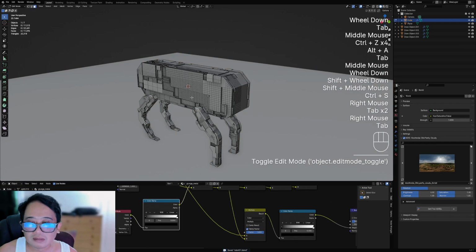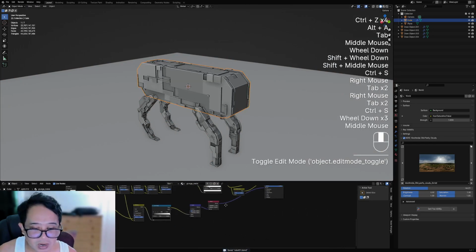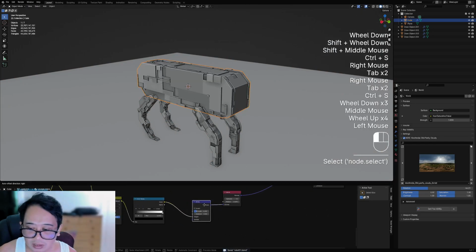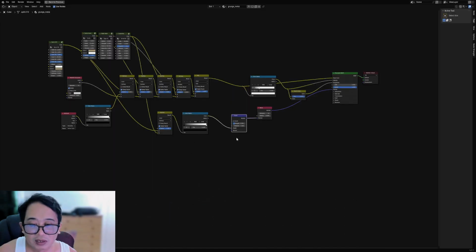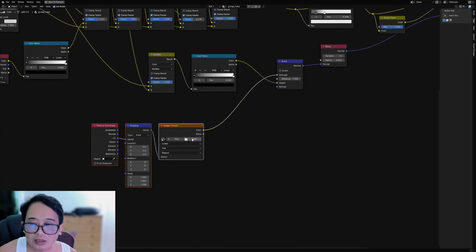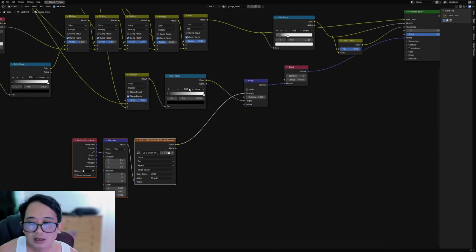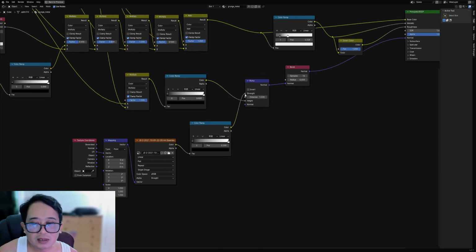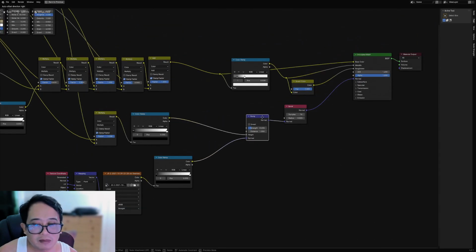I'm just going to use bump. So actually, what's the bump? Use texture to create the additional details. Displacement is one here. UV. Control this with a color ramp and set this here to normal. So basically adding the map.